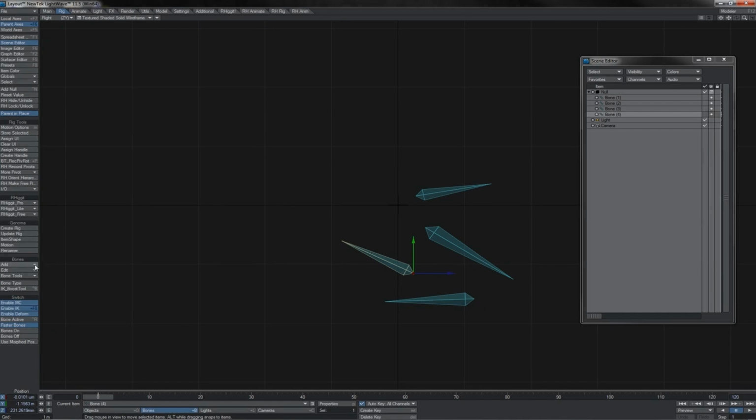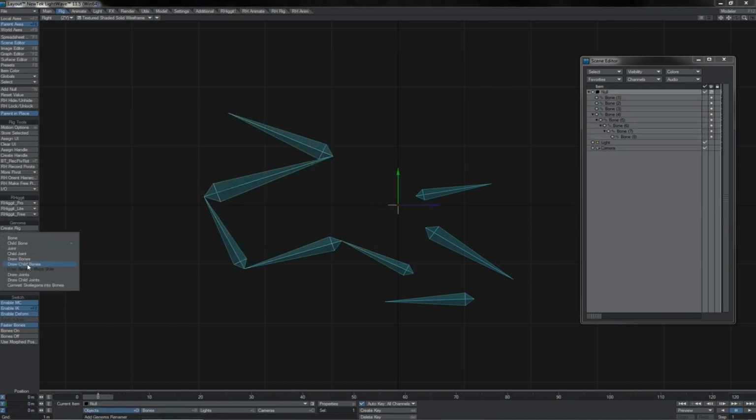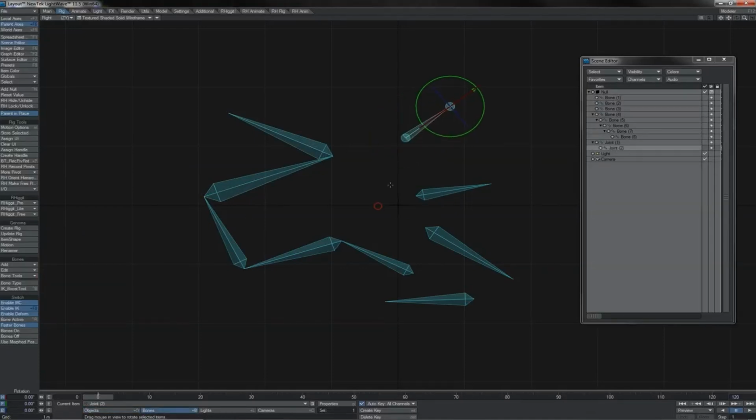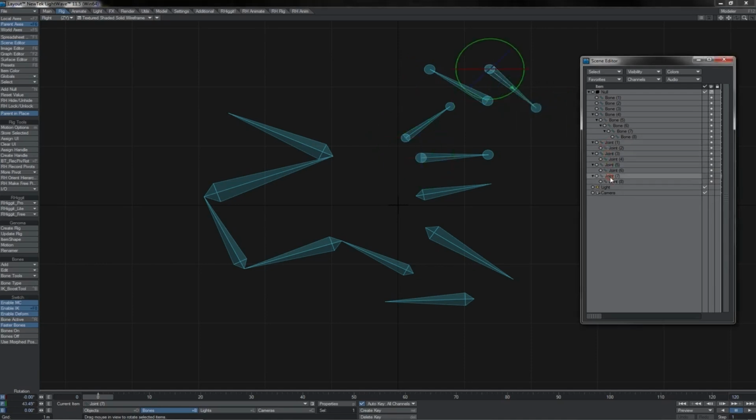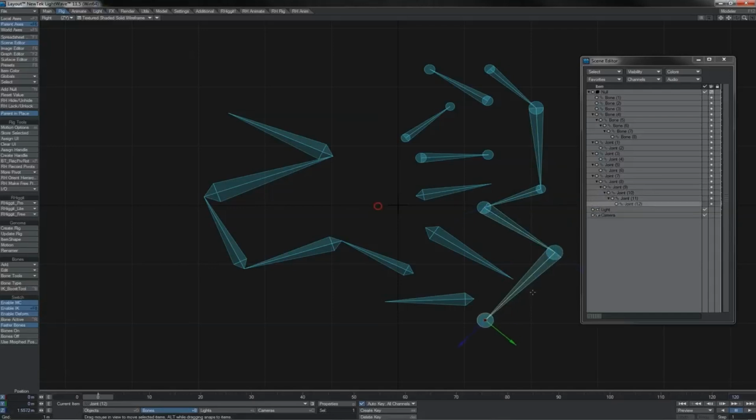To draw out a hierarchy of bones, we would use, instead of the draw bones tool, the draw child bones tool, in which case we can start drawing a hierarchy, just like this. The same, of course, goes for using joints. Doing a draw joints will allow us to draw out singular joint pairs, because these draw to give us a deformer portion. You'll notice that what you get is a bunch of little two joint hierarchies when doing this. What you can also do though, of course, is to draw child joints after drawing the first joint, and just keep drawing them out in this manner.